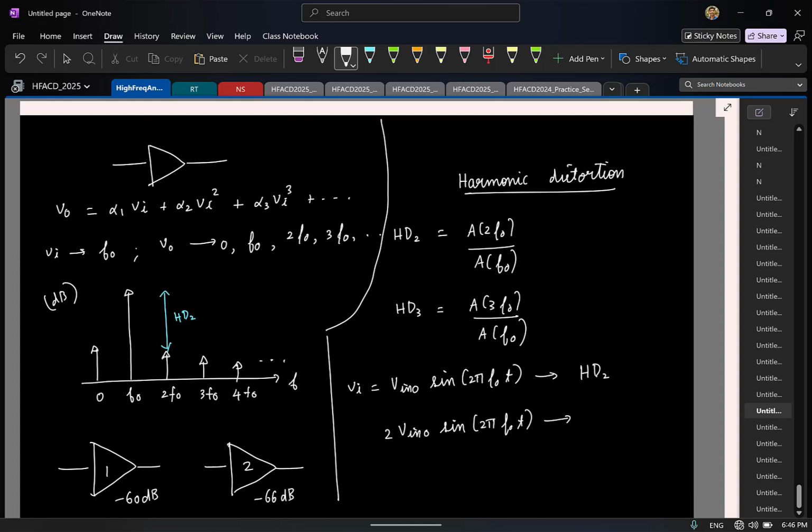So which means if I increase the amplitude, the non-linearity should be more pronounced or less pronounced? Small signals, it's more linear. If I apply large signals, will it be more non-linear, right? So non-linearity is more pronounced. Fine. So which means SD2, do you think will it remain same? It should increase, right? And you can actually compute it.